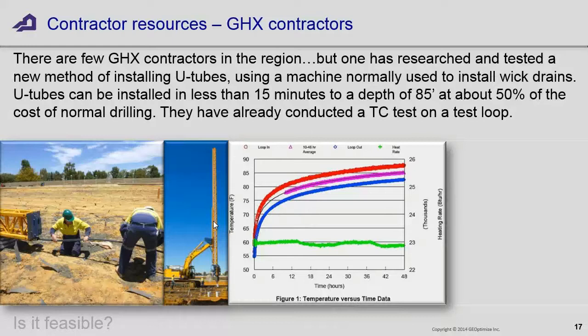You've got really soupy, sandy, silty, soft clay soil. What they do is try and drain that by inserting paths for water to drain into the aquifer below. They drain the land a bit, and they do it in the U.S. as well. They've got a mast that is about 75 feet high. They can get them up to about 100 feet high, and they can shove a U-tube in in about 5 or 10 minutes.